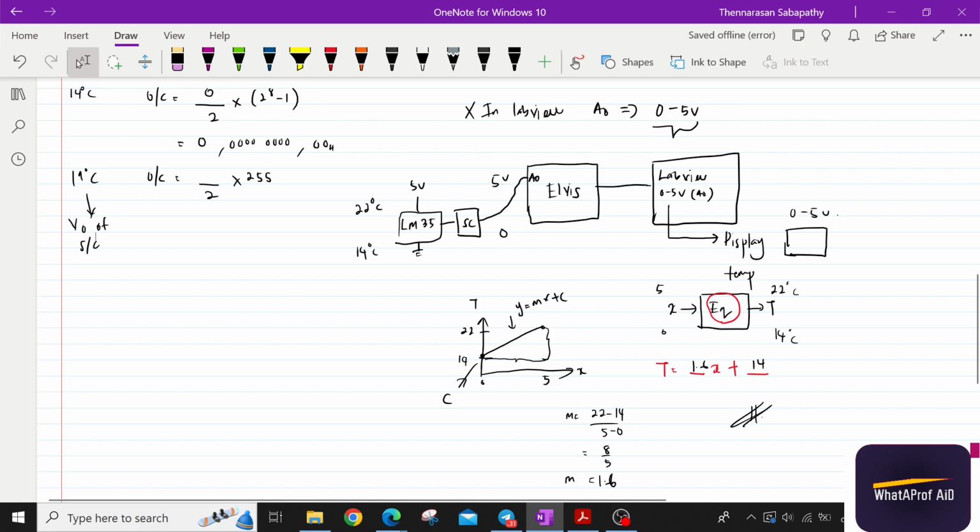Okay, so this is actually the V out at the transducer. At the transducer, you will have 19 times 20 milli, correct or not? So this is actually 0.38, right? Then to find the V out after the signal conditioning, you will use this equation.